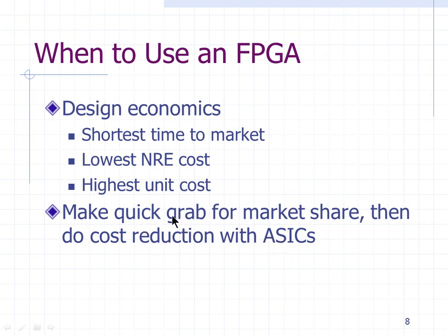So do the prototyping and the initial launch of the product using FPGAs, and later on reduce the cost of the product or offer more features with ASIC design. That was a typical method. But nowadays, as I said, FPGAs can also be manufactured in bulk, and they are. So companies who want larger numbers, somebody selling millions and millions of devices, can get FPGAs at a much lower rate compared to earlier. Very comparable to ASIC cost.